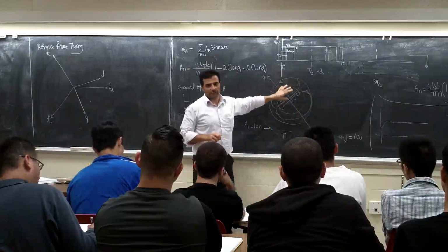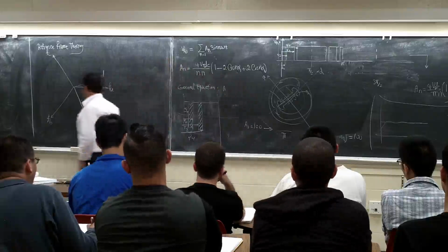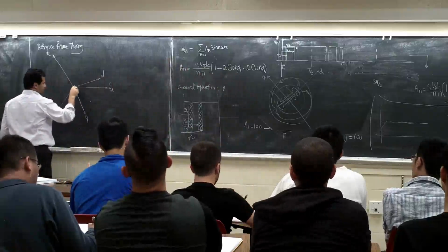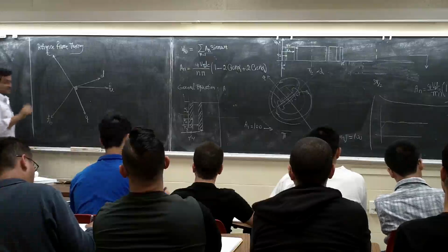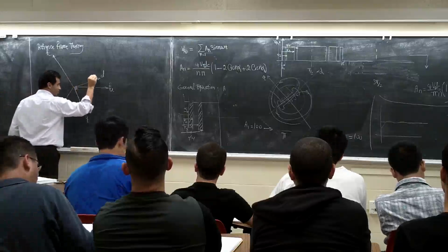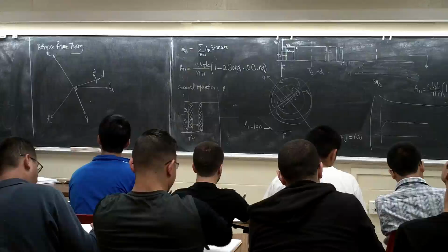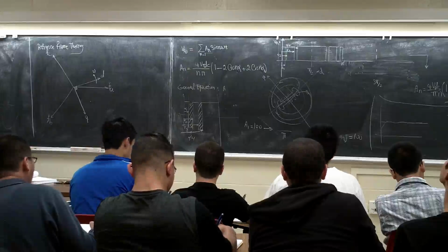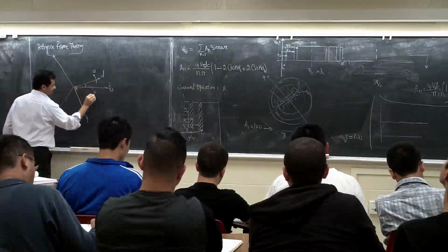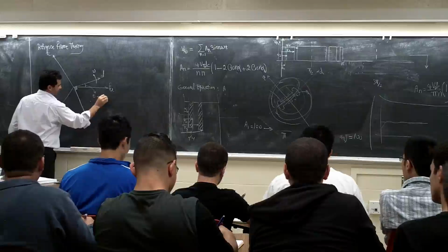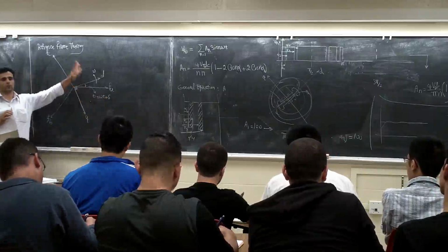They use this idea for the same thing. They say I have a three-phase system ABC, and I have a D axis and Q axis, and these two are perpendicular. Now, let's say this one is moving with the speed of omega. See, this is the important part. This one is rotating with the speed of omega, and this angle theta is going to be omega t plus delta. What's delta? Delta is the initial angle before this thing starts to rotate.